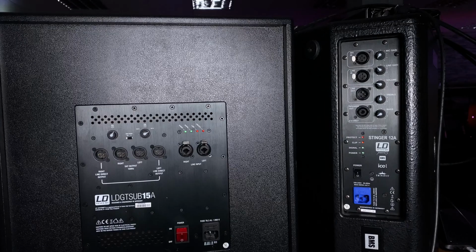Now, all loudspeakers used in sound reinforcement, subwoofers included, require a power amplifier to drive them. The difference between an active subwoofer and a passive subwoofer is the location of the power amplifier. For active subwoofers, the power amplifier is built into the cabinet of the subwoofer, while for passive subwoofers, the power amplifier is a separate standalone device. We are using an active subwoofer in this demonstration, and alongside the power amplifier that is built into the subwoofer cabinet, other processors, including a crossover, are usually built into the subwoofer cabinet as well, which we'll take advantage of in today's video.